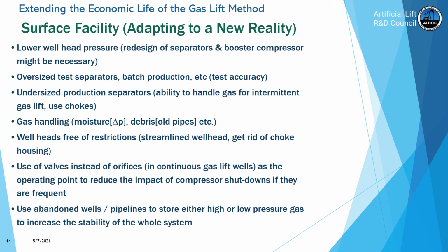Now you need to know that you're going to have to handle gas with debris and solid particles in all pipes, which might clog the pilot valve. So you might have to install some kind of filter so that the gas that is injected into the well is clean.